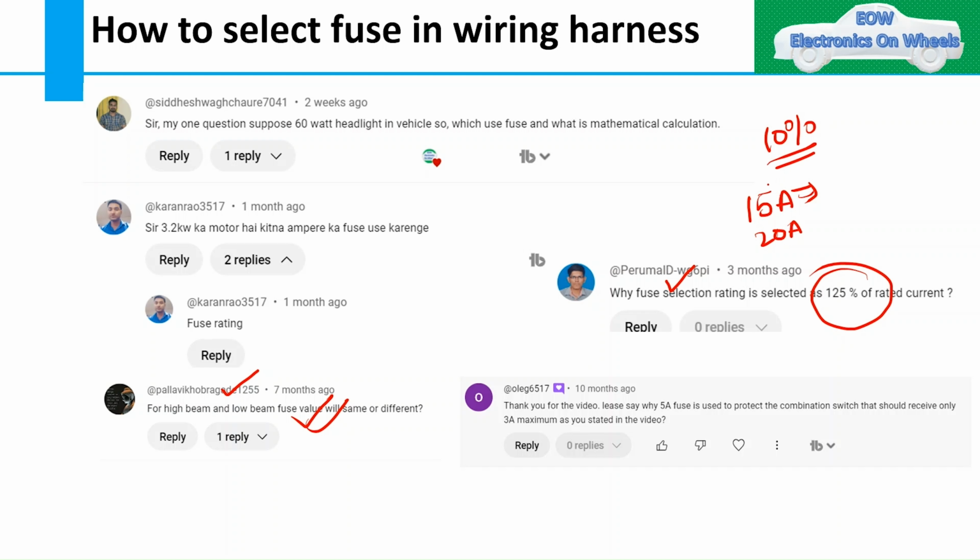Second thing, in order to avoid any aging phenomena of the fuse element over time, another derating factor of 10% we apply. Okay. So by adding all these, 10 plus 10, a 20% derating factor we are applying. And why are you not applying 5% or 8%, why only 10%? This is done based on study, right? In the labs, this is studied and analyzed that 10% is sufficient, not more, like 15% or something. So total is 20%.